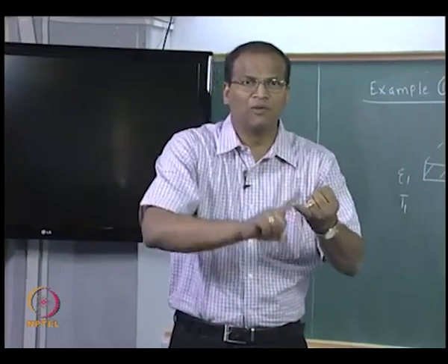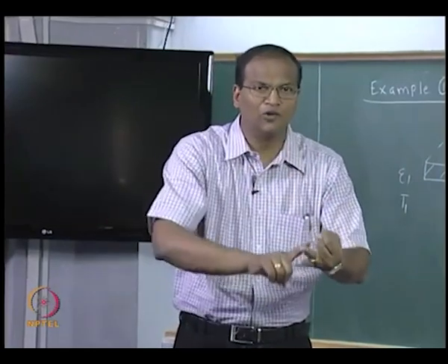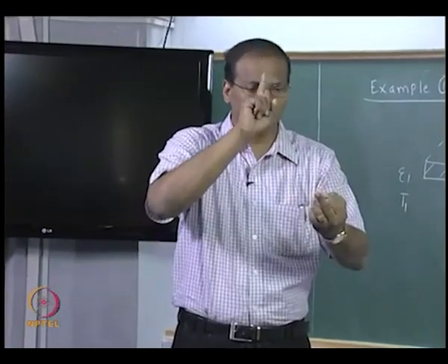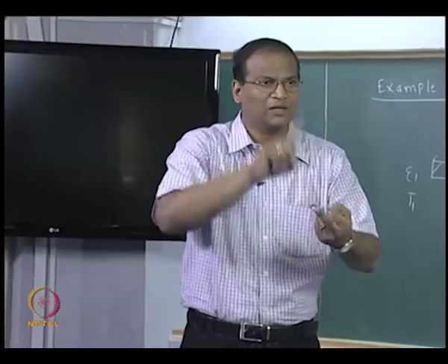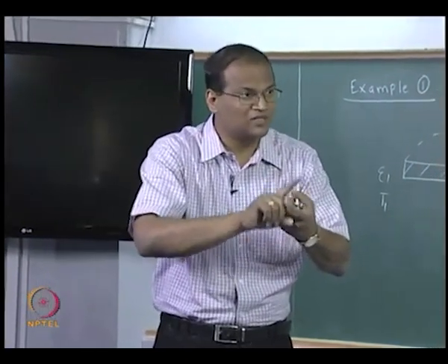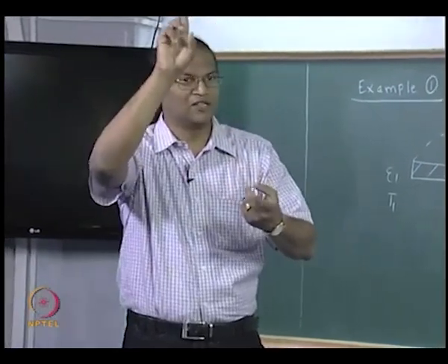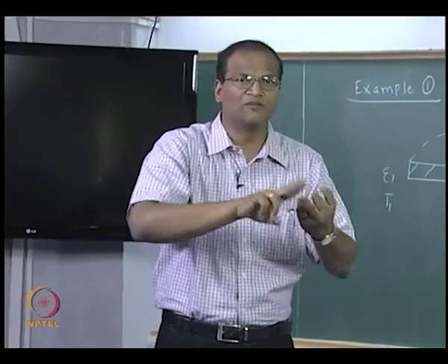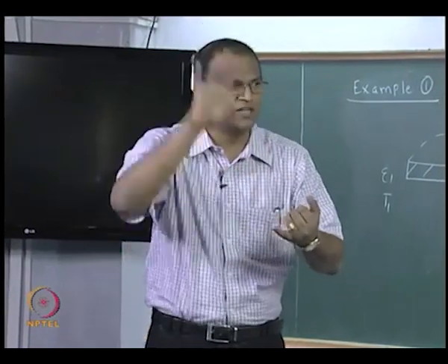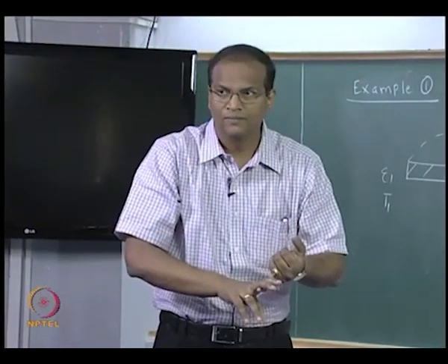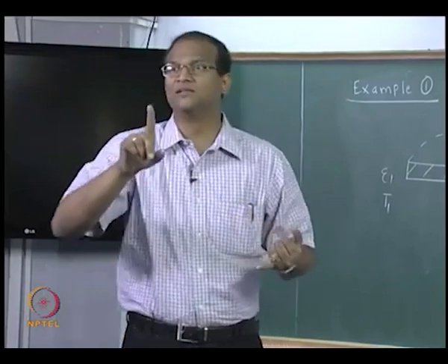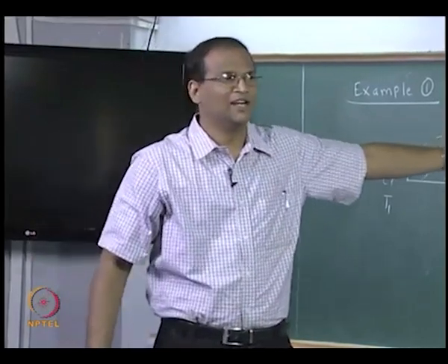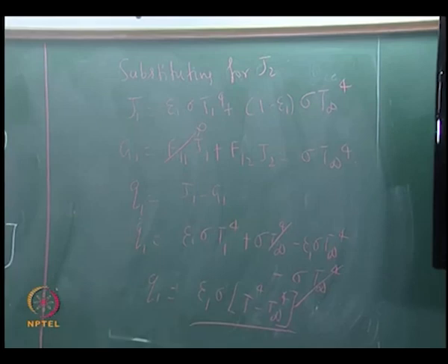Single plate at a uniform temperature, the plate is having a uniform radiosity, it is characterized by one hemispherical spectral emissivity, the surroundings temperature is constant, the temperature of the surroundings does not change, there is no irradiation from any other object, there is no other object in the vicinity. Under these conditions, it is the net radiation heat transfer from that body.